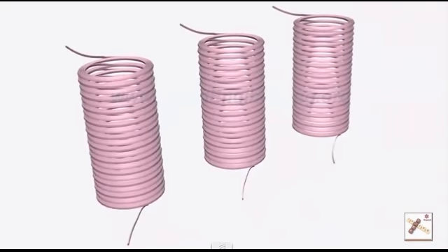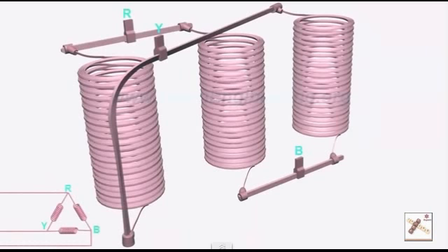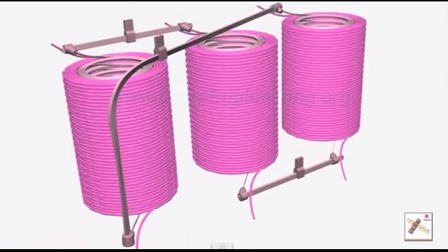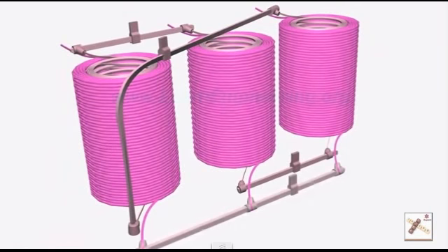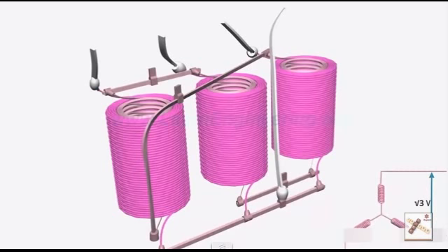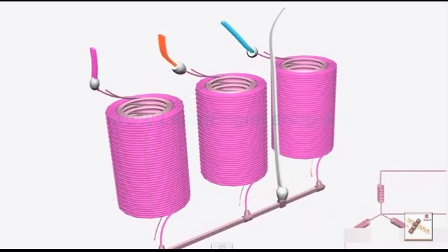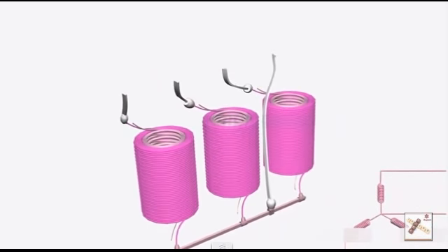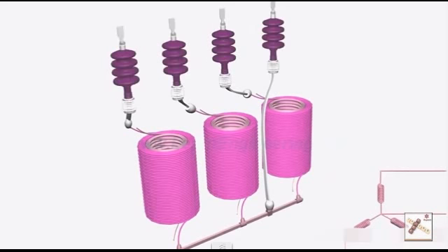The low-voltage windings are connected in a delta configuration, and the high-voltage windings are connected in a star configuration. Thus, the line voltage further rises to root 3 times on the high voltage side. This also means that, from a three-phase step-up transformer, we can draw 4 output wires: 3 phase power wires and 1 neutral. High-voltage insulated bushings are required to bring out the electrical energy.